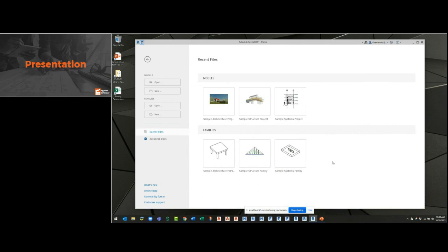Okay, so here's another thing for you guys that are project managers, model managers. When you create your content, you're going to want to create libraries with versions of years, so you can have at least 2 or 3 years of the same content managed, updated, purged, audited, opened, and saved. That'll keep your families from getting corrupted. There are some bulk updating options in here as well.